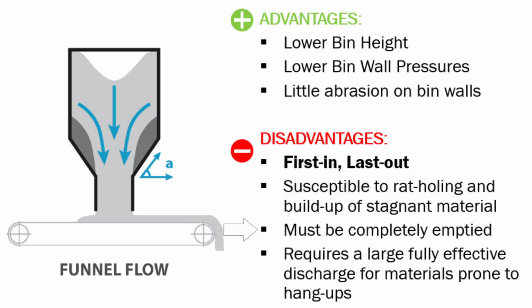And the third disadvantage, and this is more of an operational issue, is that you should really be emptying out your funnel flow bin on a regular basis. Otherwise, the material that is sitting stagnant will never move and potentially rot or become rock hard.